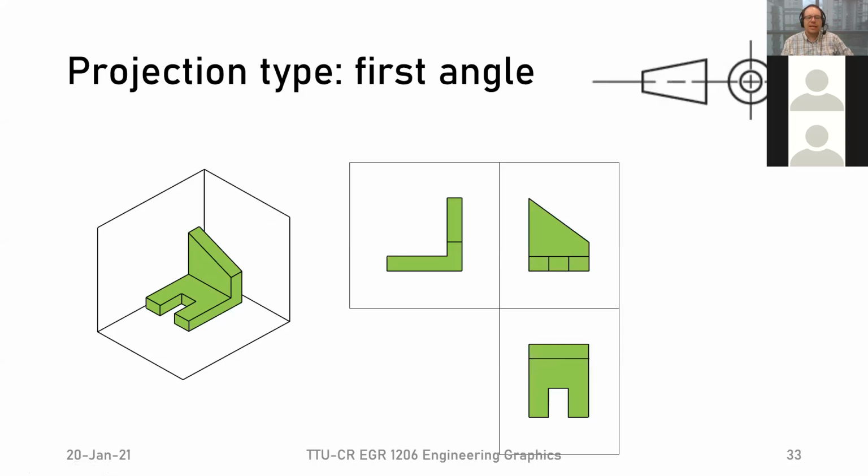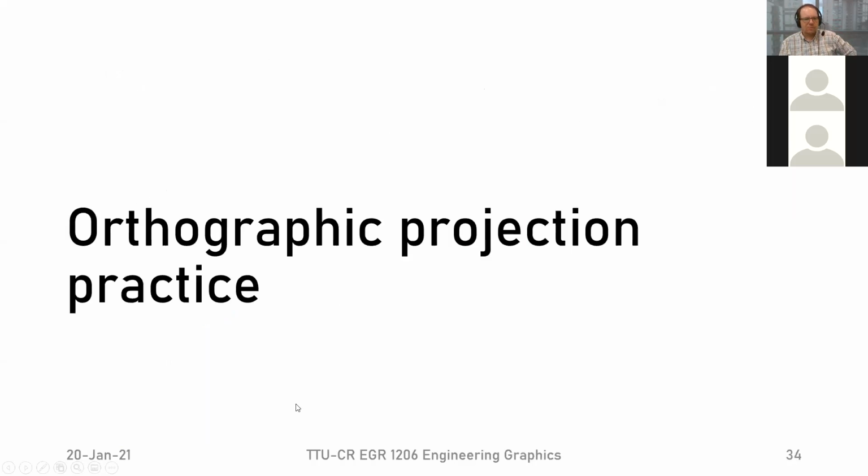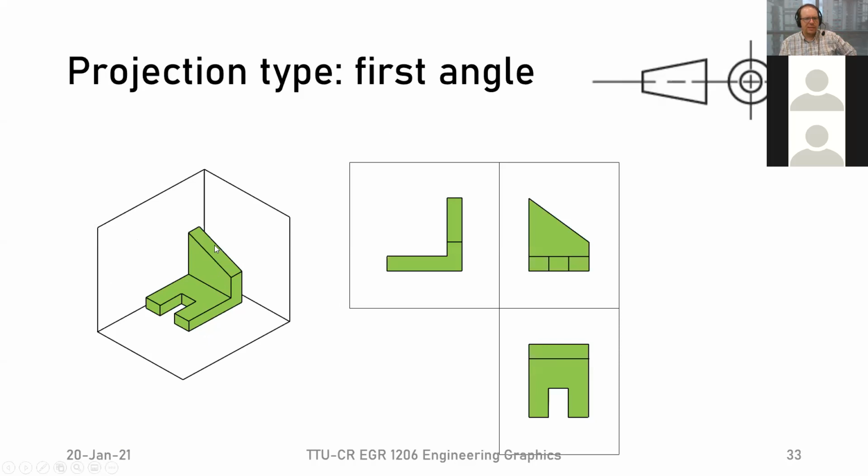But now we can also do it slightly differently, and that is what's called the first angle projection. The symbol for first angle projection is here. The idea is that instead of having the glass box, I'm surprised, I thought I'd gotten rid of some lines here as well. Oh well. Basically, instead of looking on the outside of the glass, we're now looking at the inside of the glass, and we're using this back glass pane right here as our main one. So we're taking whatever we can see and projecting it back onto that screen right there.